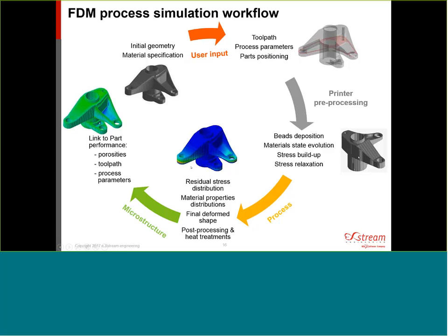What will be simulated is the actual deposition of the beads. We will see afterwards that, of course, we cannot afford to simulate exactly the full manufacturing process bead by bead, but we have a very efficient multi-scale approach where we can do some pre-computation and then only simulate the layer by layer deposition. After this simulation, we obtain the residual stress distributions, material properties distributions, and very importantly, the final deformed shape.